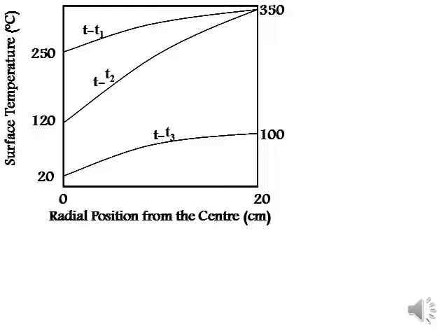In the third moment, you will find that now water reached all regions, so that the farthest point dropped to 100, and of course because the points of impact are the most lucky to get cooling, they dropped further to 20. So the farthest point dropped to 100, while the nearest point to the impact dropped to 20. So this is the realistic distribution of the temperature in the spatial domain and in the temporal domain.